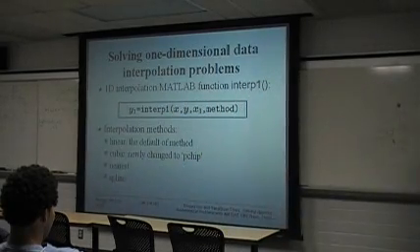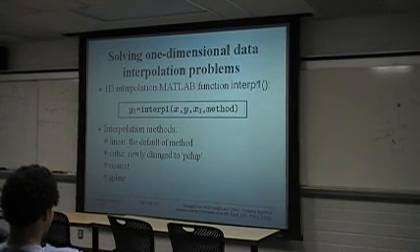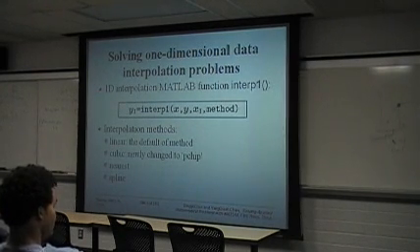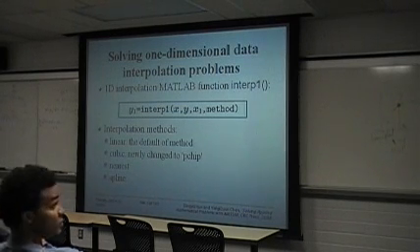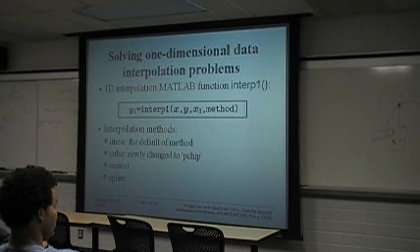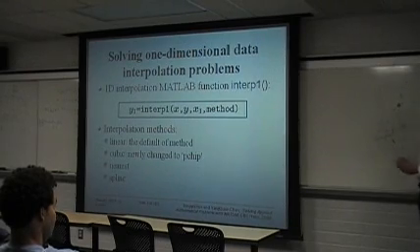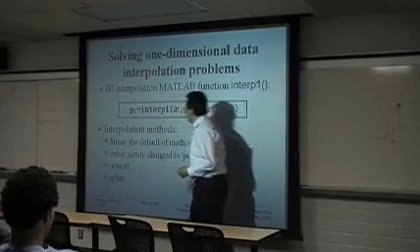So it seems to be quite simple to solve this kind of problem with the use of a Matlab function. The method we can use is the linear one, just drawing them by lines. And also better methods such as cubic or nearest. Nearest is not a very good one. We can use cubic or splines. We have such options as the method.